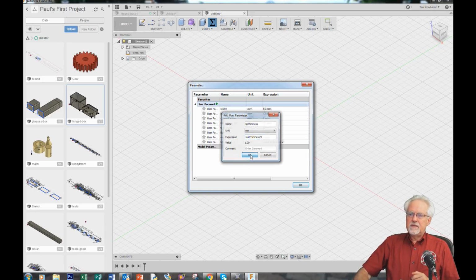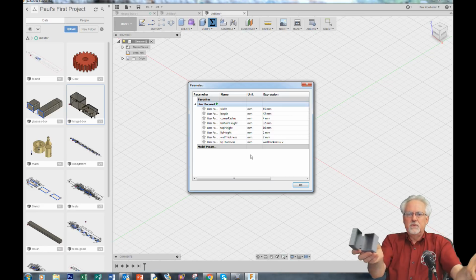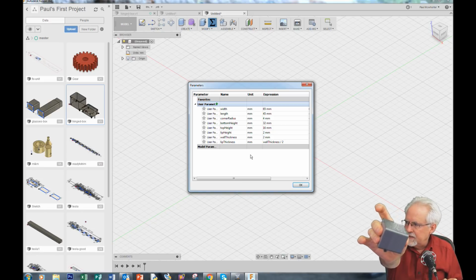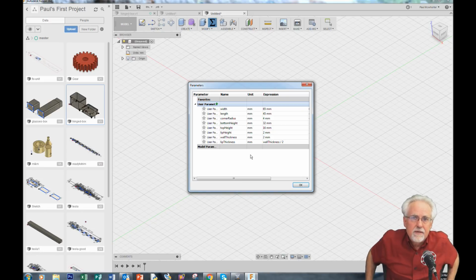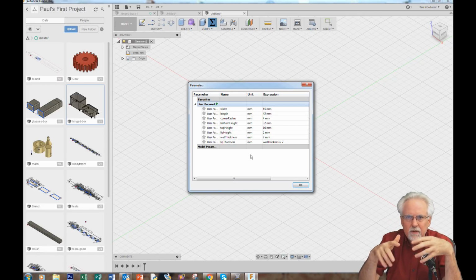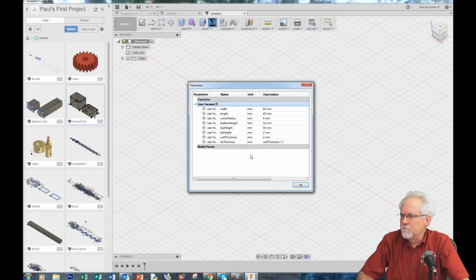So what that means is that whatever thickness I make the wall, which is what I would want to design to, I'm always guaranteed that the lid is going to snap on nicely. Okay. Think through this. Think how you want this to work. Setting up the battle is won or lost a lot of times in setting these parameters up right. Okay, that's pretty good for most of it.